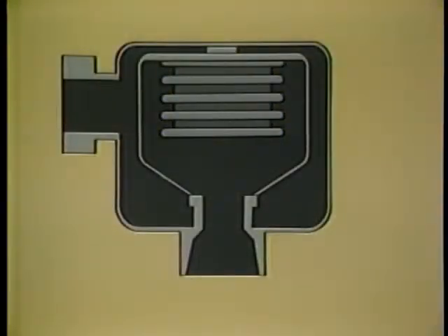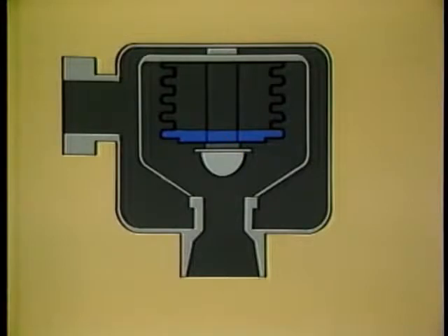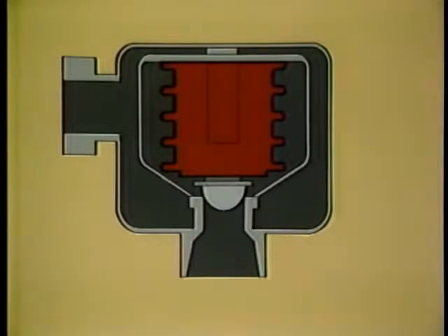One end of the bellows is secured within the body of the trap. The valve is located at the opposite end of the bellows. When the bellows charge vaporizes, the pressure inside the bellows increases. A sufficient increase in this pressure expands the bellows to seat the valve.